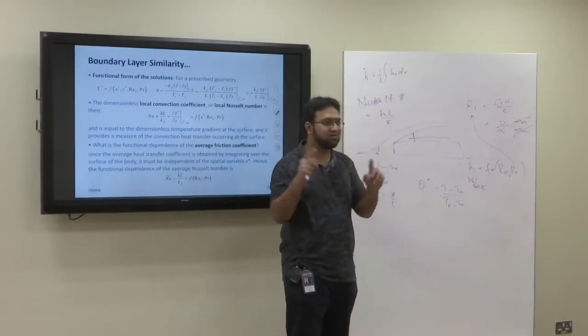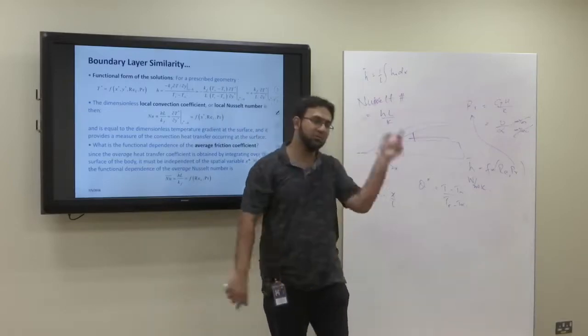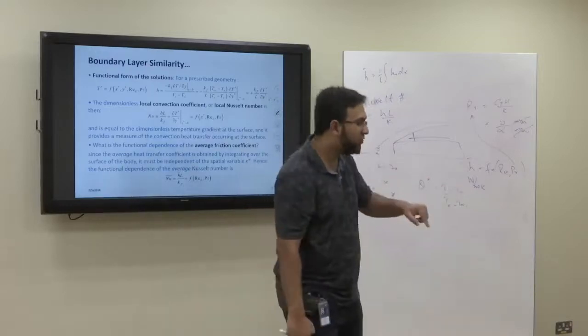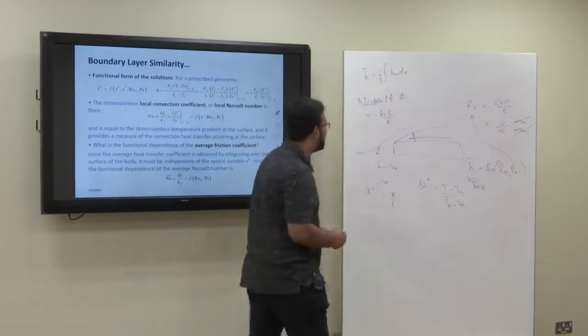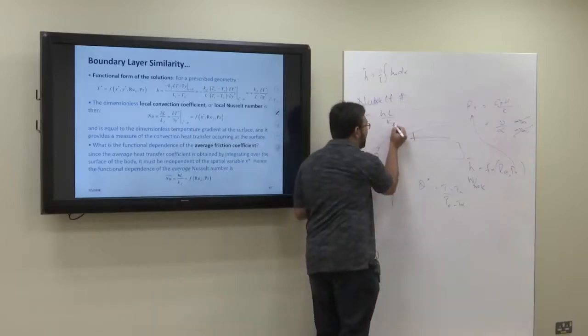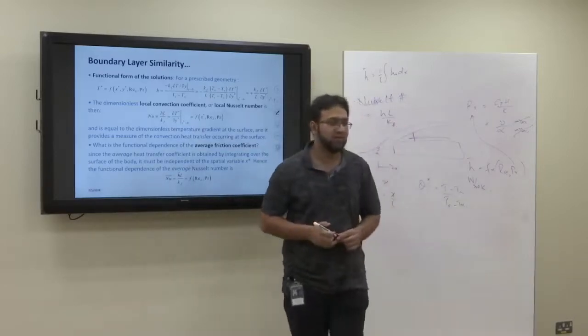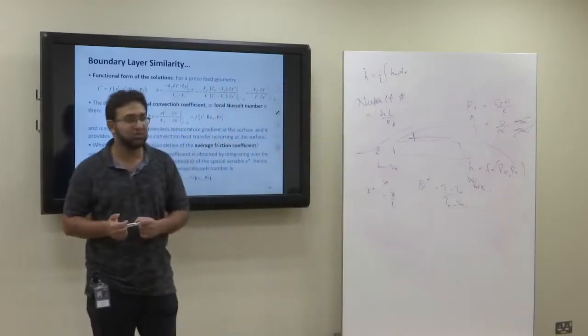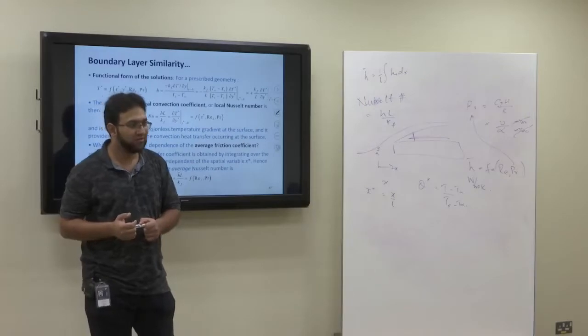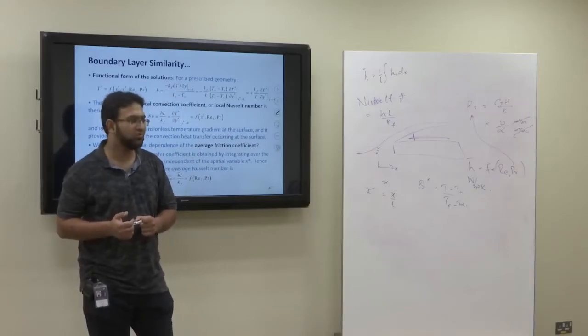In case of Biot number, sometimes they confuse it the other way around. Instead of putting the k of the solid, they put the k of the liquid. Okay? So it's k_f, fluid. Is it clear? Same formula, hL upon k. But here k is of the solid. Here, for Nusselt, k is of the liquid.